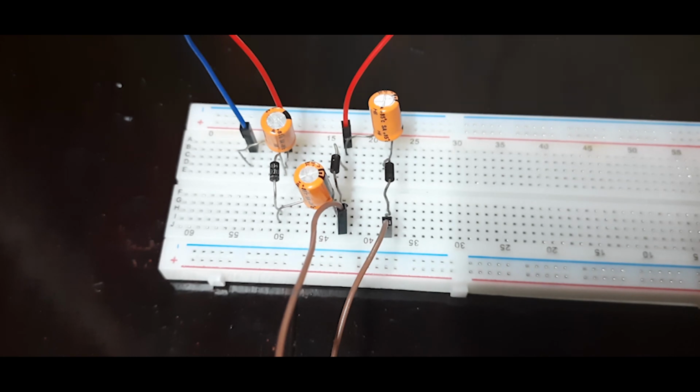Why you need to do this is because the capacitor would already be charged to a VP value. Say if the VP value is, in our case, around 8. Now, if you reduce the input voltage to say 3, this VP will be stored here and that will create an error in the output. So before changing the input, make sure that you switch off the input and do this discharging of the capacitor and then charge it to the desired value again. Then only you will get the correct output value. So please note this point and repeat this experiment for various input voltages. Thank you.